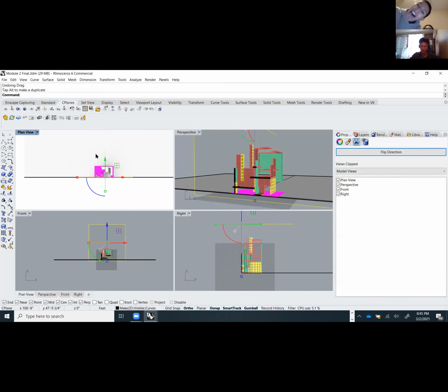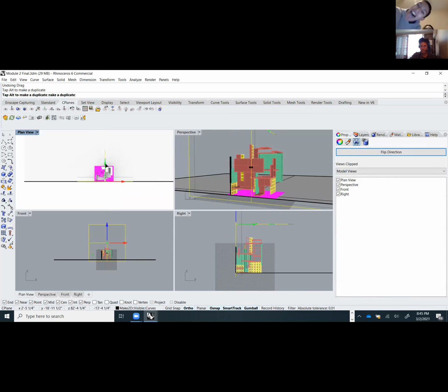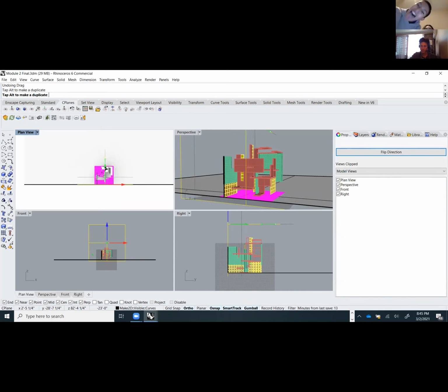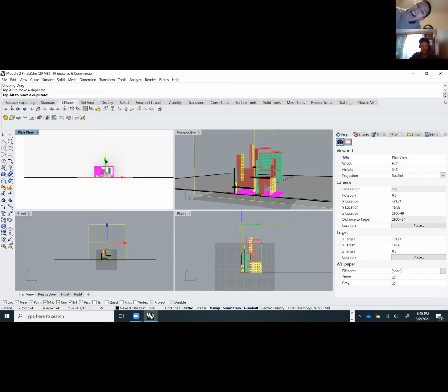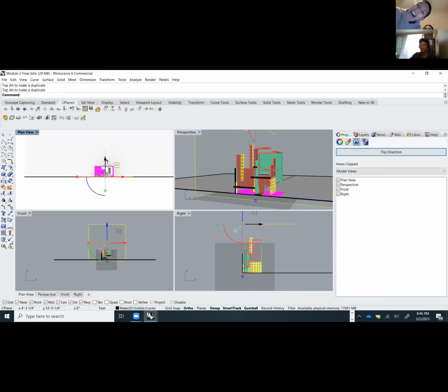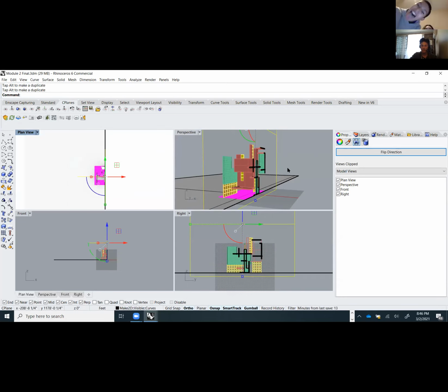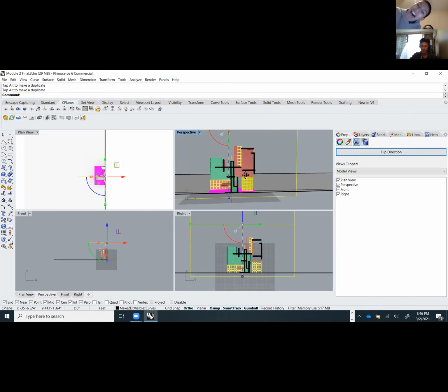Any questions so far? So you really just want to look and see what looks pretty interesting. I don't really like this angle or this side that I'm cutting through. Maybe I want to take a look at what it's going to look like if I cut through the other side. So what I can do is click this blue arc and rotate it 90 degrees. And now it's just going to flip that clipping plane, so now we can look at it this way in our perspective view.